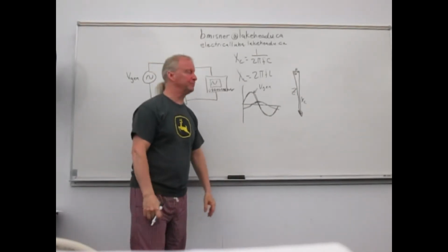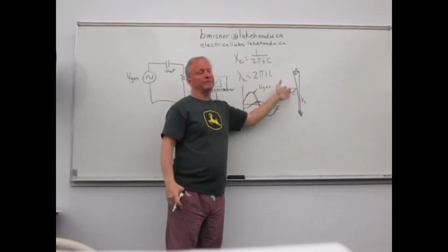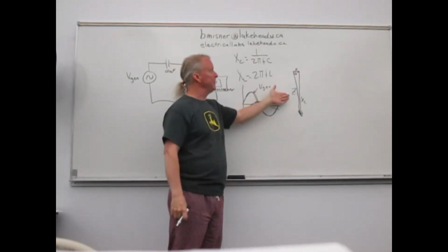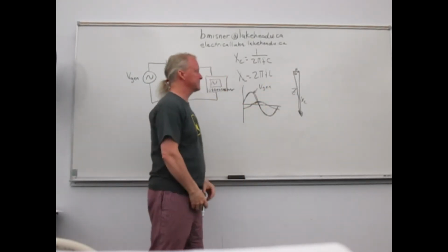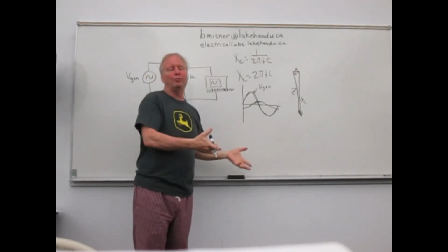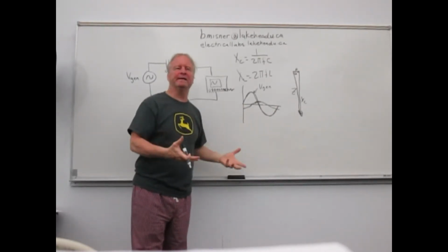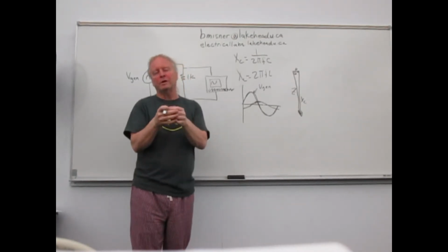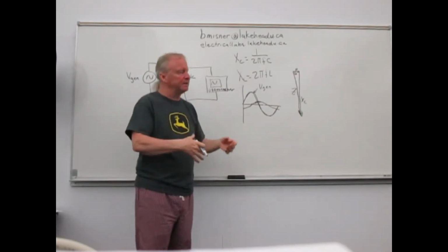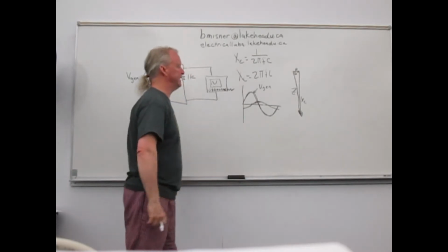Okay, so we're throwing around some new terms, right? XC, that's the reactance, and the overall resistance of the circuit, the impedance of the circuit is Z. Okay, so that's why, like, if you buy your speakers and they're 8 ohm, well, 8 ohm, okay, that's resistance, but they always call it impedance, right? Well, because there's more, it's not just a pure resistive thing, a speaker, right? It has inductance in it. So it has an impedance, not just a straight resistance, okay?